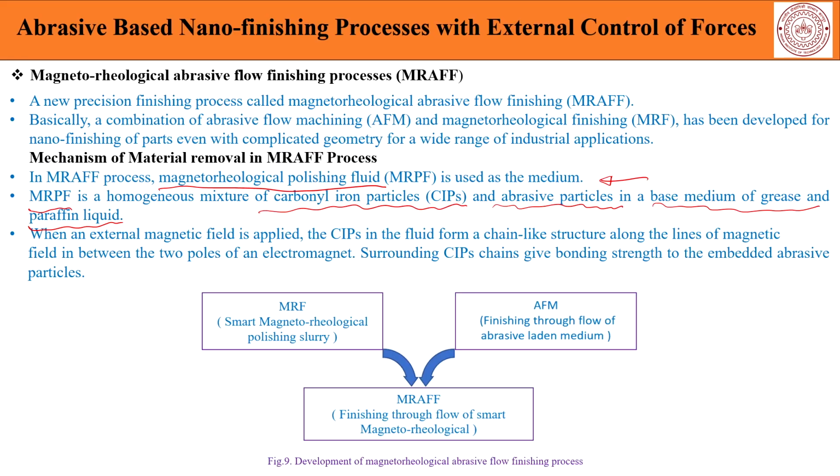And depending on the strength of the magnetic field, the magnetization of the material, and the various other phenomena associated with the field losses, or let us say the susceptibility, the magnetization ability, you can have a range of viscosities obtainable through such external actuation.